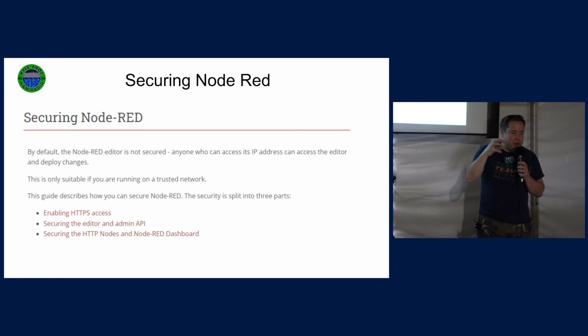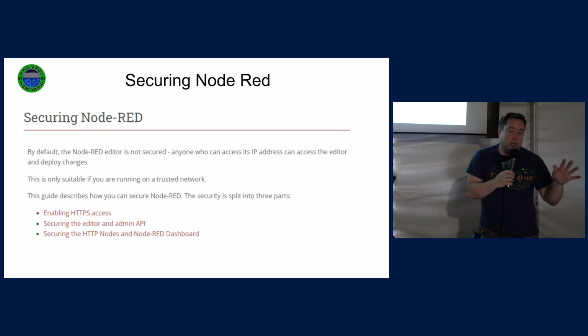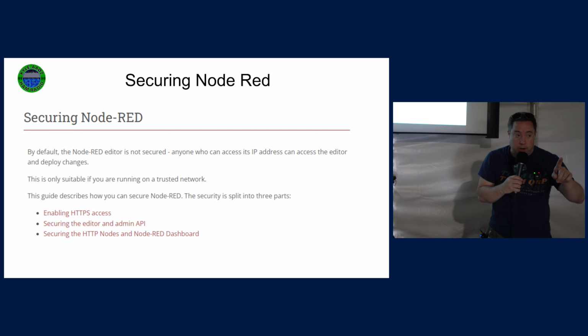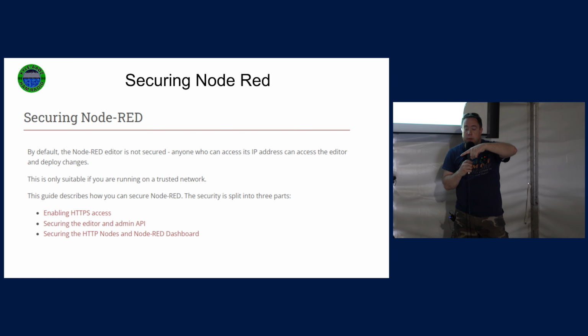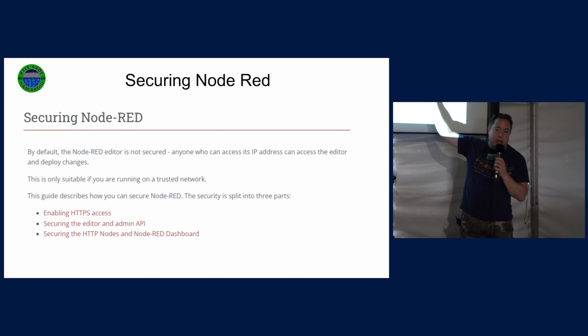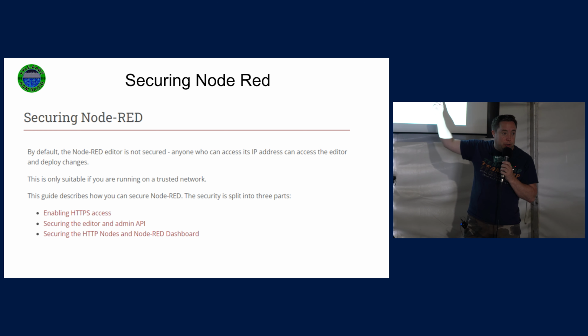There is something you can do to secure Node-RED. So if you're thinking about running this remote, you can. But I would not trust the security on Node-RED. Okay? Whenever you install Node-RED by default, there is no security, right? If you can get to that web page, you can get into your Node-RED flow and change it, right? So if you expose port 1880 to the internet, guess what? Everyone in America, everyone in the world can get into your Node-RED flows.